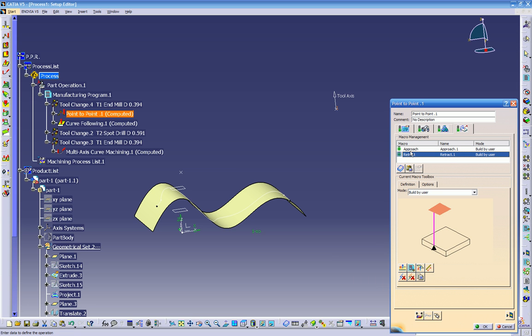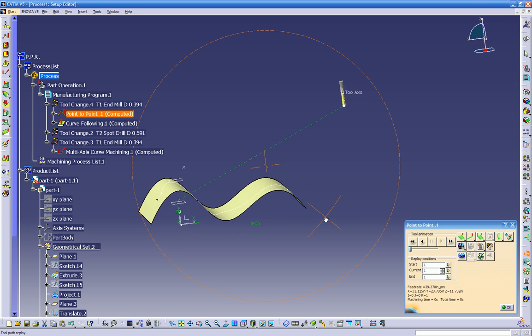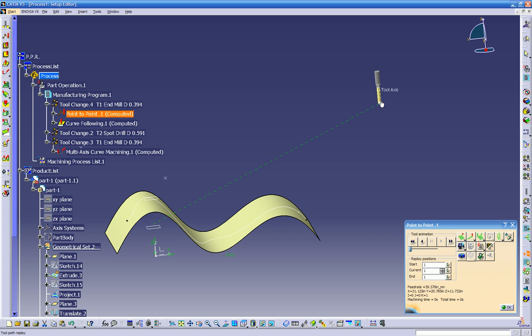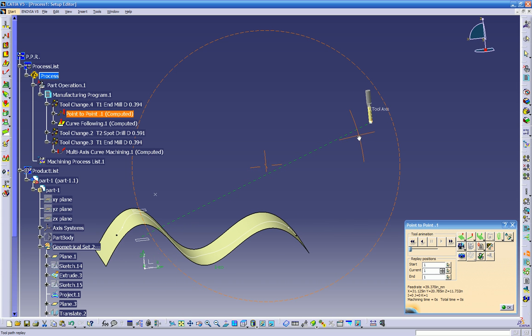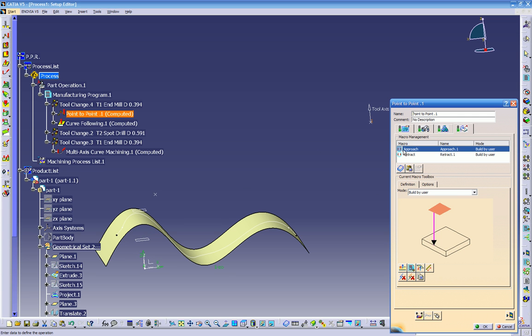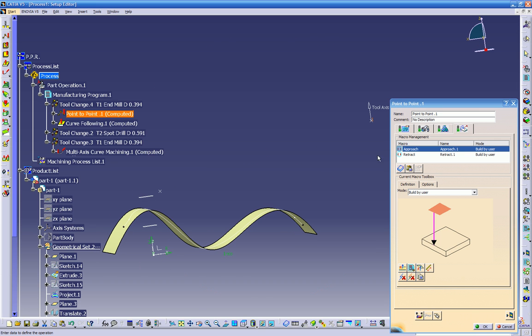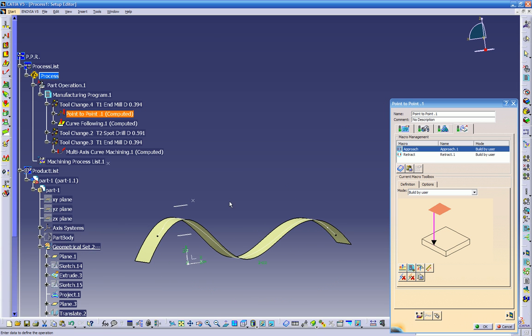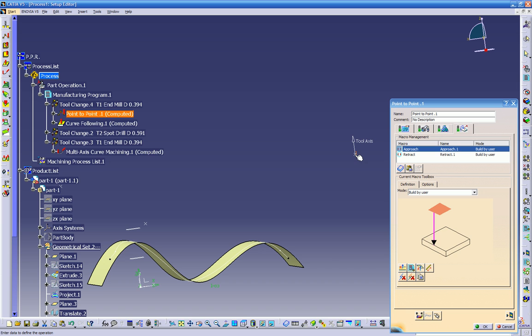Let's see what option we have in here. So I'm going to deactivate this, click on here, deactivate, and let's do Toolpath replay. There we go. So as you see right now, our point is going to bring the tool right into that point that we created. The reason it's coming down is because we have this plane here activated. Approach, I was trying to go to this, but you can put your retract and approach however you decided. So we cannot use this option right now because it's going to ask us to choose a plane, and if you look at the plane, it's way below this tool, this point.